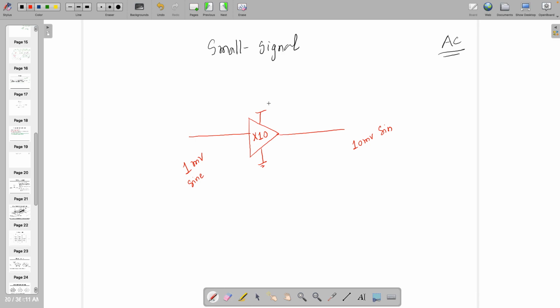But what if this is 1 volt and I apply here a 0.5 volt sine wave, what will be the output? It will get clipped at once. Correct, right? So this is very simple. It might be something like this, clipped at 2 points, one at this point and one at this point. This will be VDD of 1 volt and this is ground or 0 volt, which is given to this circuit. If it is 5 volt and minus 5 volt, it will be there only.